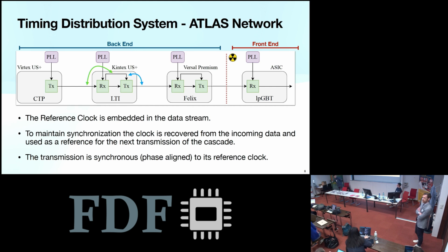Quick question. How do you generate the helper frequency for the HPTD? So the helper PLL, the Skyworks PLL we use as a jitter cleaner, has the possibility also to create this frequency. So we just program it with the ClockBuilder, and it's compatible.